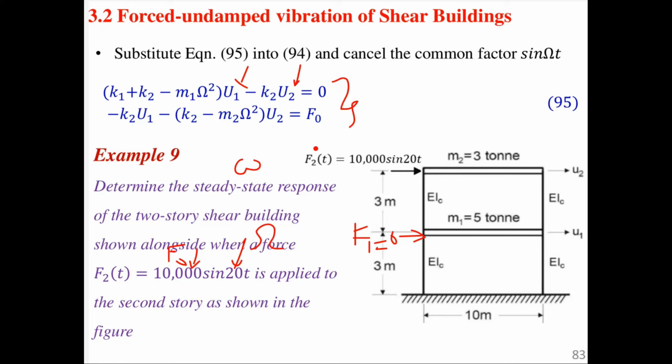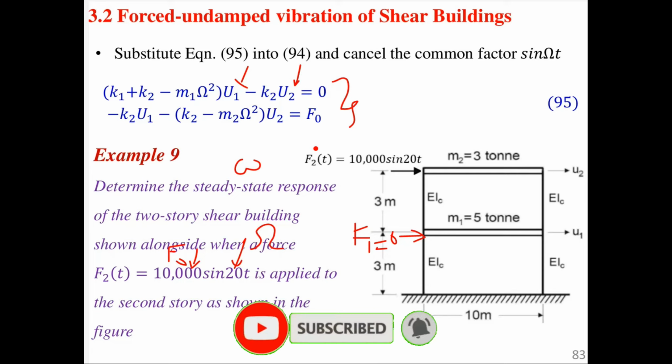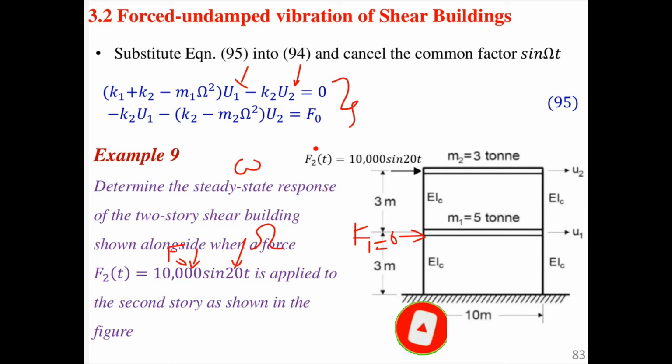So when you are doing an analysis using software and an error comes up, you go to the error report, the message report. For example, if I'm using Abaqus, I view why my analysis stopped. You might find it says resonance occurred, or it may use another term, like negative eigenvalues. With the knowledge I have now, that if resonance occurs our structure has already collapsed, I'll be able to interpret that, because the software only gives results in terms of numbers. It's for me to understand and explain what has happened.